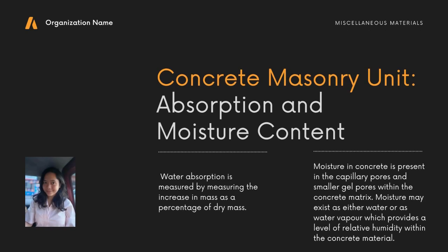The moisture condition of aggregates in concrete is very important. Compressive strength of concrete is dependent on the ratio of mass of water to cementitious material, but what isn't understood as well is that the water-cement ratio controls the pore volume and pore sizes in the concrete, thereby determining not only the strength but also the durability. In the laboratory and when designing concrete mixture, we really talk of only two moisture conditions.